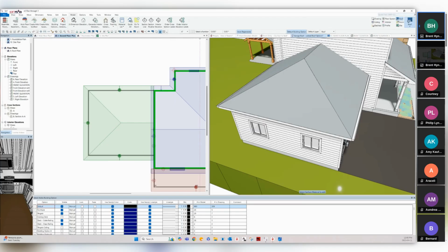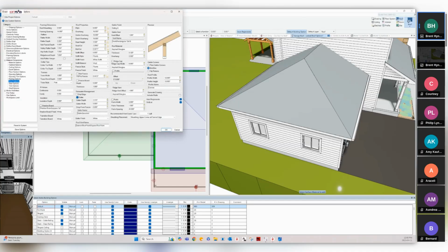We are in roof mode, and if we go to draw and we go into roof options, you're going to notice a few changes to the items: pitch, overhang, heel height, seat cut, and boot cut, as well as your top to fascia, which is down under the subfascia area, down in here, okay? There's a little lock icon to the right-hand side of the calculator.